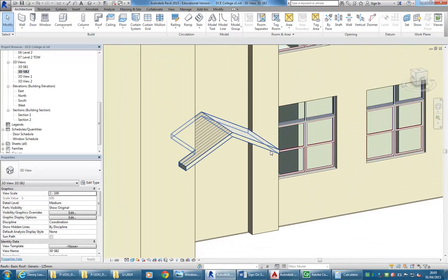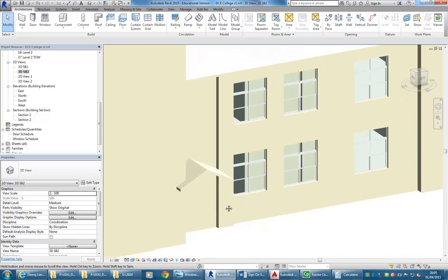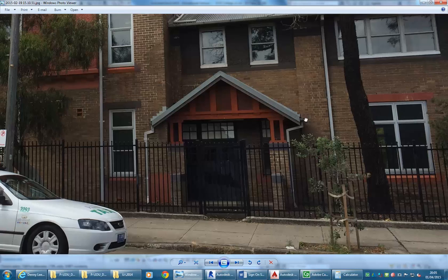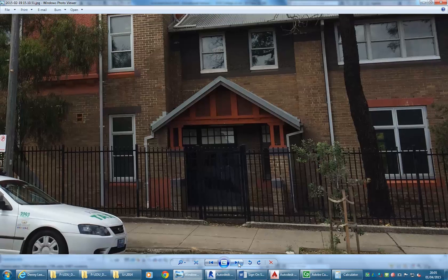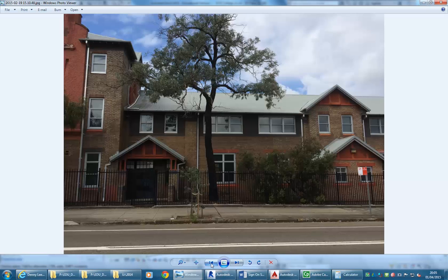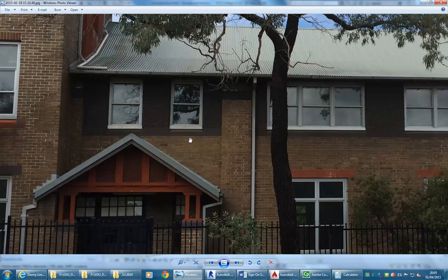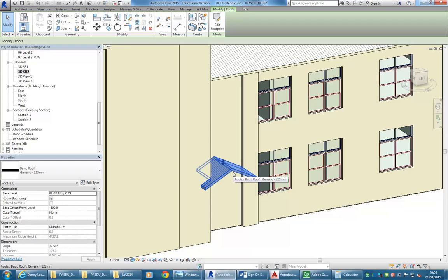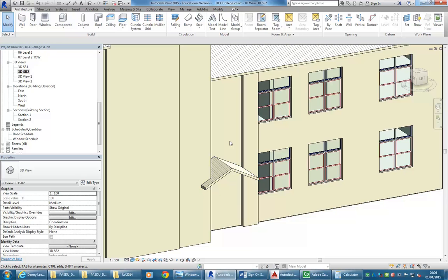And so then once you have that located, I'd probably go a bit further and work on those window positions, which I can again see in the photo here, and you can check that as well. Yeah, so it's a bit different to what I've drawn. And you can count bricks going across to work with that properly. I've obviously done it too narrow, but then you can model the piers in underneath the roof. And like I was saying, don't try to use pick walls there to set the slope, because it'll probably end up being uneven. Pick walls works a bit differently.